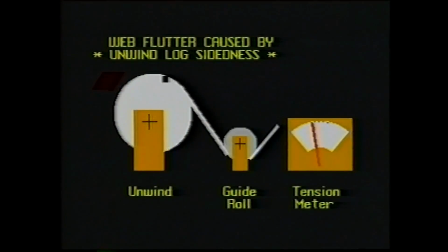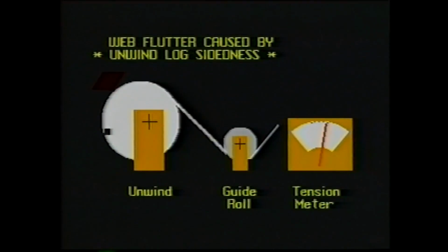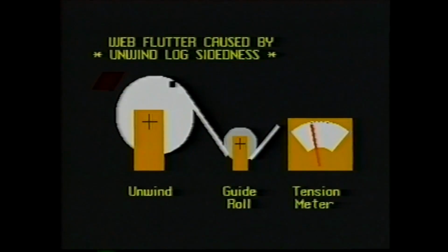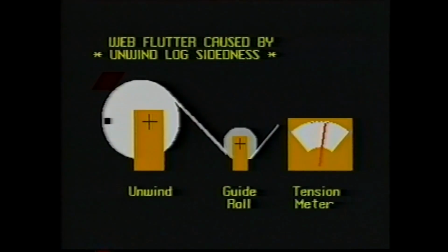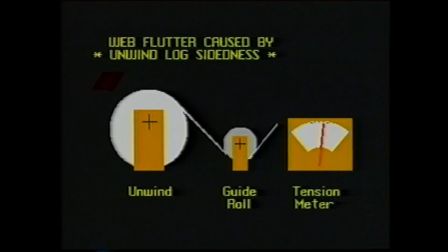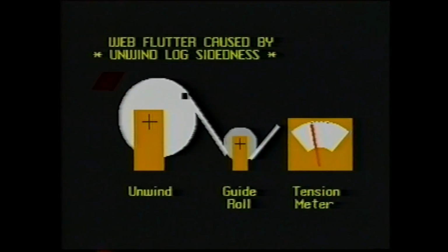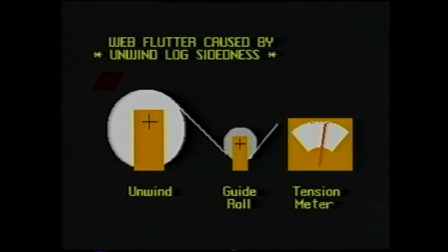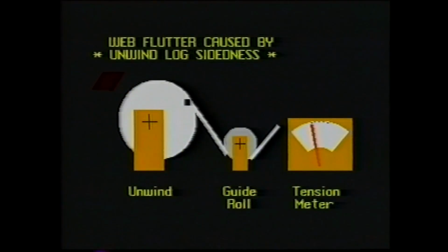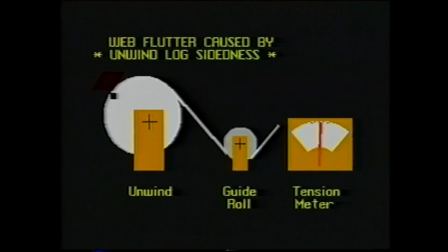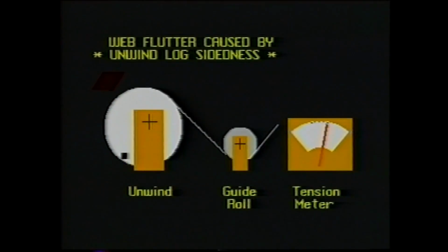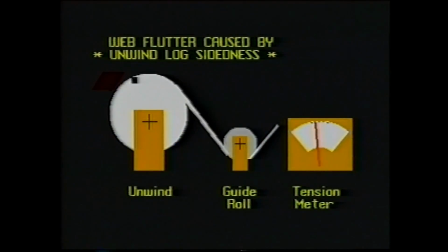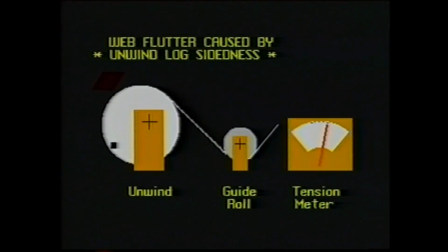To keep a log concentric from the time it is wound until it is ready for unwinding involves good reel handling practices. The log should not be set on the floor, bumped against other logs, or loaded roughly into the unwind stands. Also, if the logs are going to sit for a while, a Sunday drive should be considered to slowly rotate the log. Additional requirements for a stable sheet run include a well-tuned tension system and drive, as well as short draw lengths.